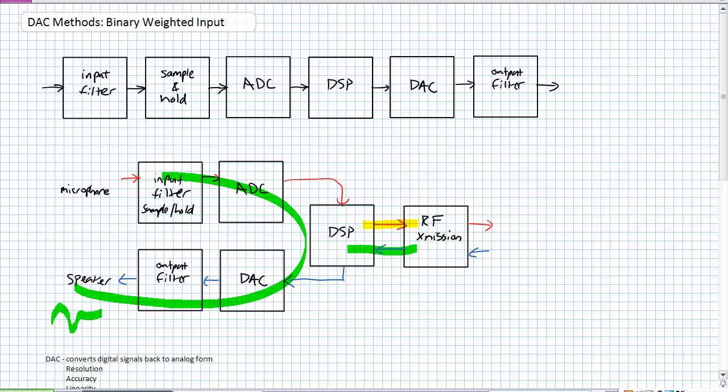One quick note here too about the actual construction of the DSPs. They are very similar to a microprocessor. Like I said, there is a memory and a CPU. Most DSPs have what's known as basically a two-memory, a binary structure. There's a program memory and a data memory, okay? Because it's handling these things in real time super fast, you want to have data memory separate from the program memory.